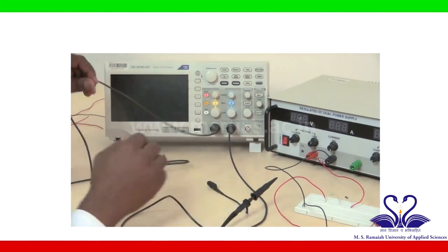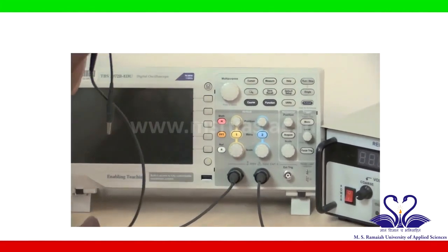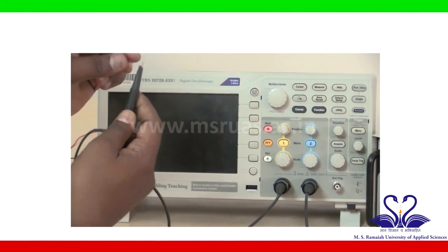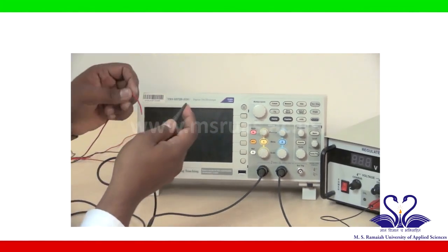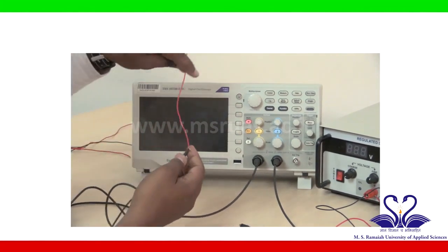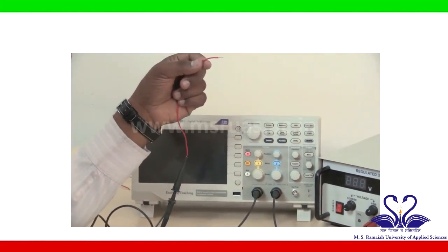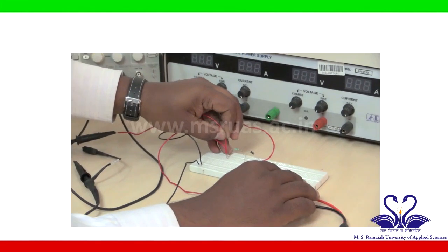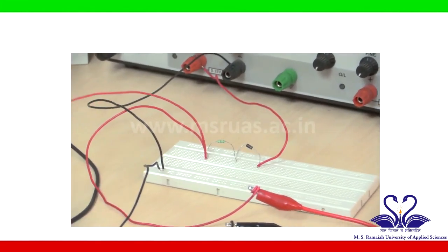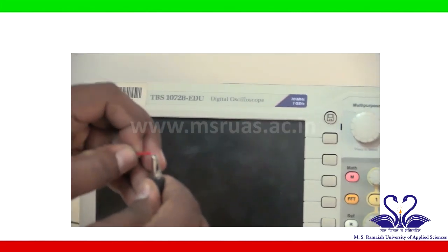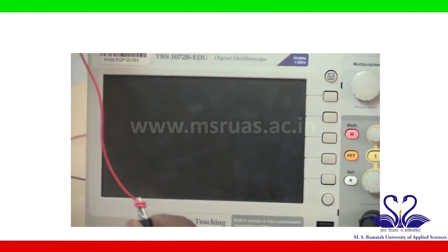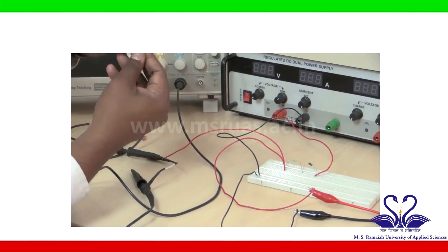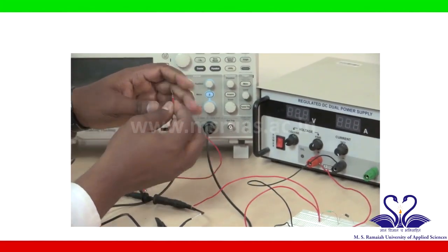The first channel probe I will connect to the place where the input is connected, that is, the positive of channel 1 is connected to the positive of the input. If you see in the circuit, this is the input positive, I will connect this to the positive of the input, and the negative of channel 1 I will connect to the negative of the input. If you see the circuit, this negative of the input is here, which is connected to the ground. I will connect this to the ground.